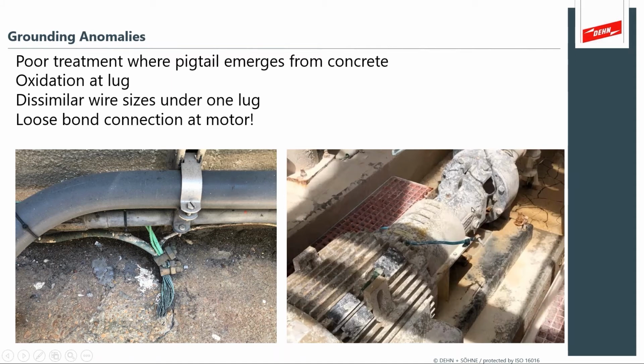Off here to the right, you've got a motor stanchion grounding that's not even connected. So it's going to be very difficult to troubleshoot problems with the instrumentation when it's floating, not bonded. So here we have a direct problem where the instrumentation and the earthing on this motor is going to lead to instrumentation failure because the motor is not bonded.